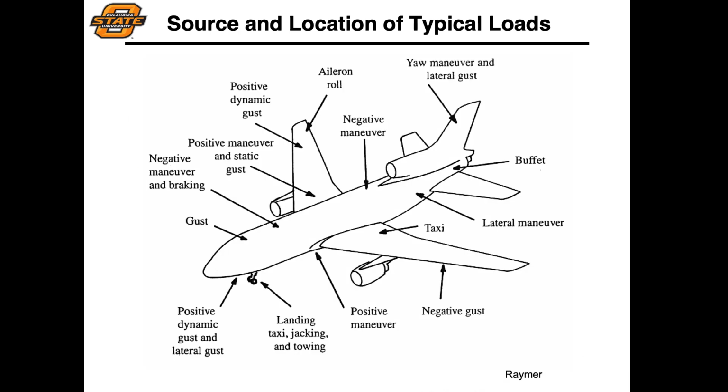So those loads are going to be acting on various places across our aircraft. We can think about wings as one example, but we'll also have to design the empennage, the fuselage, and things such as how the loads acting on individual elements, such as landing gear, are transferred throughout the rest of the aircraft. Because any load acting at one part of the aircraft is really going to affect the entire aircraft as well. So we have to think about the load paths and how those loads are actually being transferred from one part of the aircraft to another part of the aircraft.